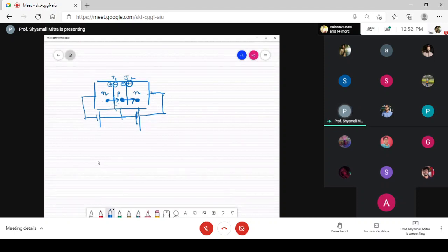So the problem with this diode can be circumvented using a bipolar junction transistor, but there are several conditions imposed on it before we can harness this minority carrier, which is of utmost importance in this case, before it recombines with any of the holes, which are the majority carrier over here, and finally comes up to this region. So the problem is clear to you. Now we have to make some arrangements so that this minority carrier in this p-type region is not lost, and we can collect it onto this end region.